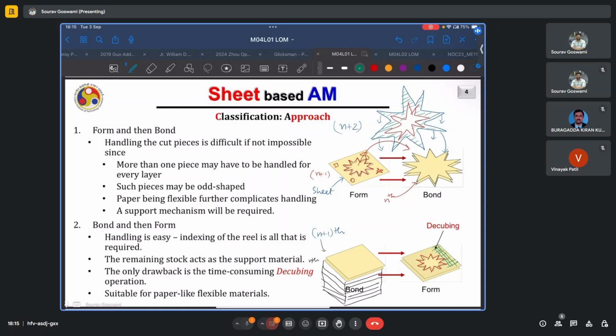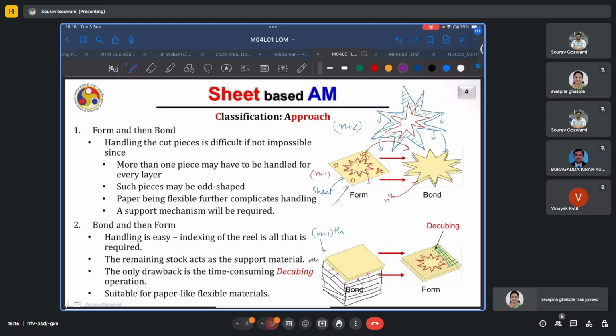And one thing you can easily notice is that in this case, the machining operation must be very precise. In the previous case here, say you might have some sacrificial plate at the bottom, and thus you could be a little lenient with your machining in terms of the depth of machining that you want to achieve. So even if you cut a little deeper than you intended, it's okay because there is only some sacrificial plate at the bottom. Whereas in this case, there's already a previously deposited layer here and some region which must have been scanned on that layer. And so for this new n plus 1th layer that you are now depositing, if you were to cut deeper than the intended depth, which nominally is equal to the thickness of the sheet itself, you will end up damaging the previously deposited layer, which is highly undesirable. So in this case, the machining must be more precise, and we must exercise greater control over the machining aspect, specifically and especially the depth of cut.